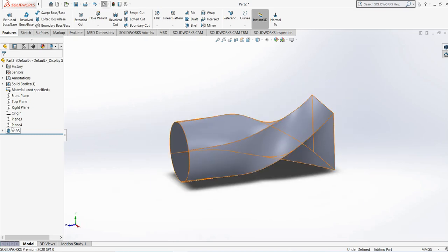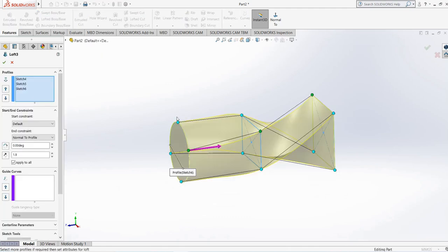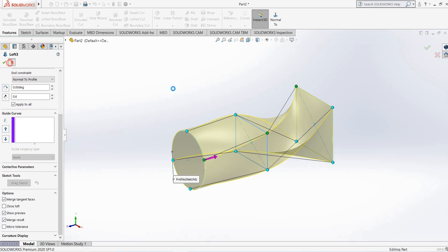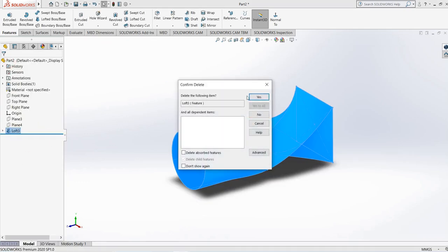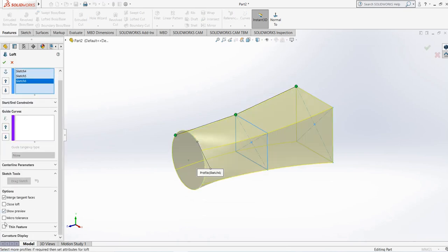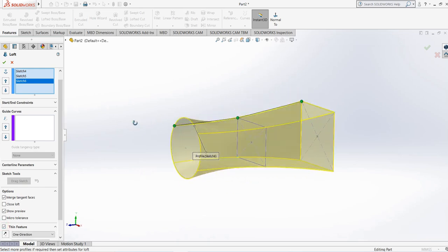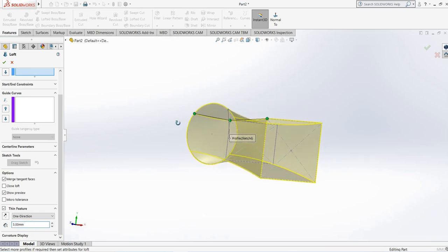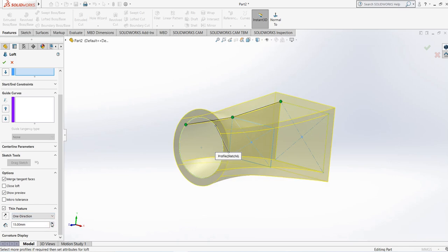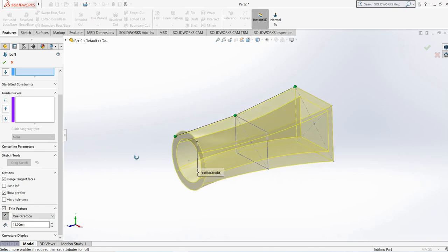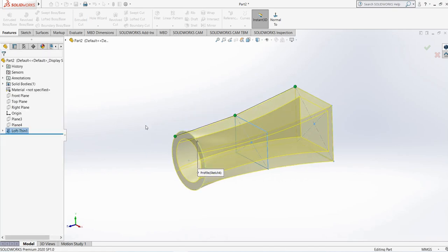You can see we have this type of structures. Basically, we can make so many structures using this loft. Okay, or let's just go for this. We can also have this, let me delete this one. We can also have this option called thin feature. So we already know what thin feature is, so we can go for this option, and you can see throughout the structure, and we can go for this thickness 5 mm. So you can go for 6, 15, whatever you need, and it is going outside, we can change it inside, right? And we can complete the sketch.